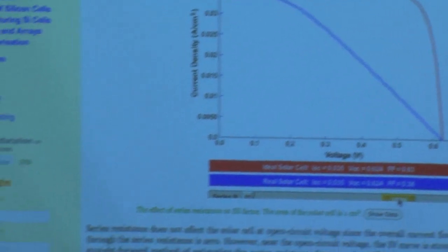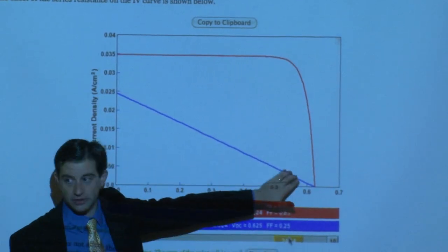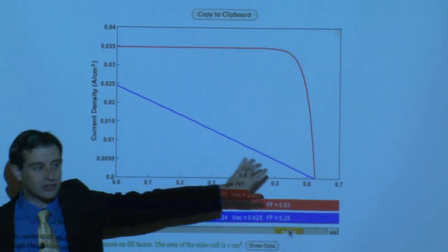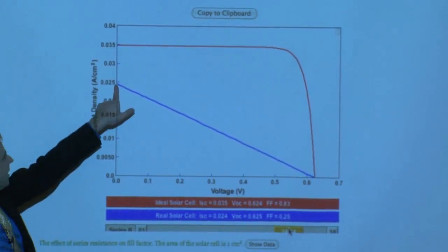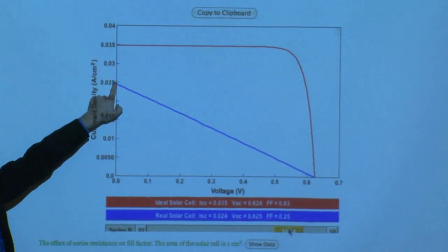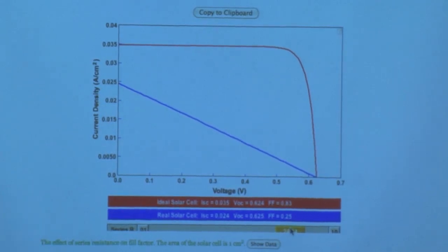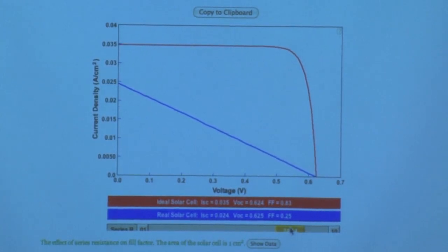So if you were to do an extreme condition, you might have so much series resistance that your IV curve looks like a straight line. You have an ohmic resistor now. The resistance component is swamping out any diode-like behavior of your solar cell, and that's why you have a line. Likewise, you're dropping the total current output of your device, right? Because you have a resistor in series now preventing the current flow. OK, so that's, again, an extreme case of what can happen.